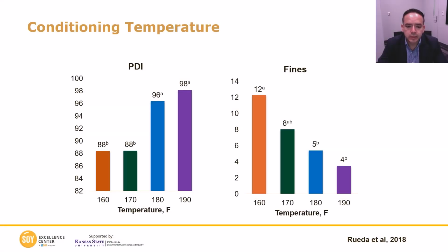And conditioning is extremely important. I was telling you that as you increase conditioning temperature, you improve pellet quality. And we did this experiment in my team, and we were increasing the conditioning temperature from 160 to 170, 180, and 190 Fahrenheit degrees.